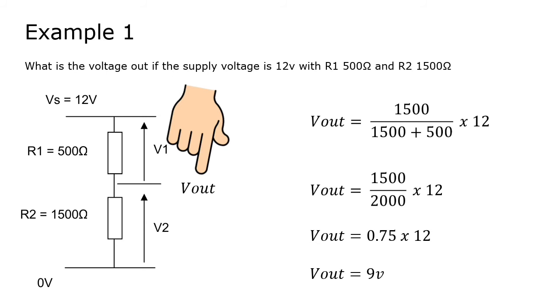So now this is where you can use different resistors to control that voltage further and reduce it further as well. And what you might end up doing is using a variable resistor, so that you can actually adjust the resistor instead of having to swap resistors in and out constantly. You just have one with a dial that you can dial up, or a slider that will be able to slide up more resistance on it, like a potentiometer, which is a variable resistor in this case.